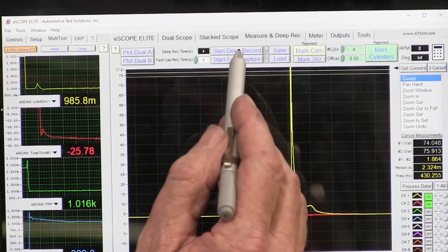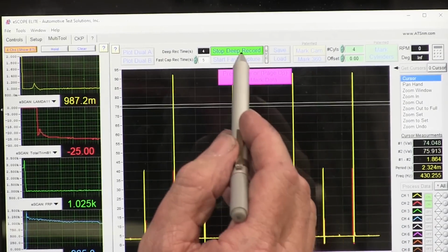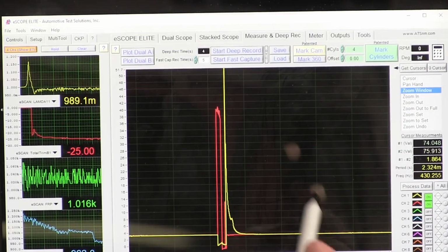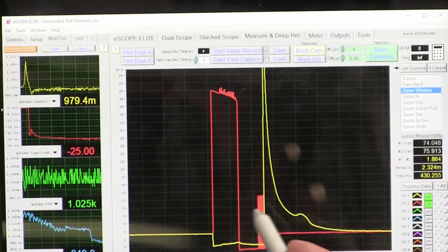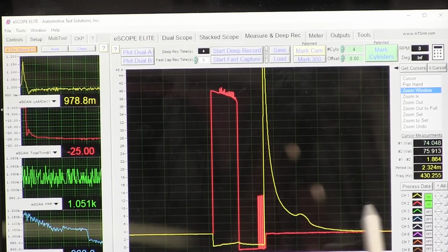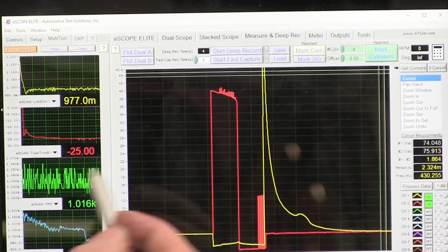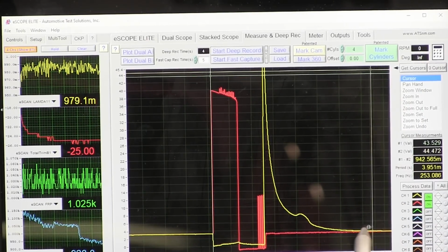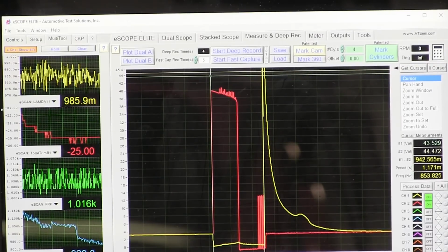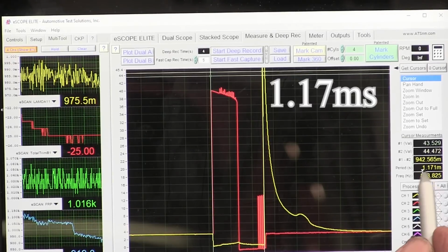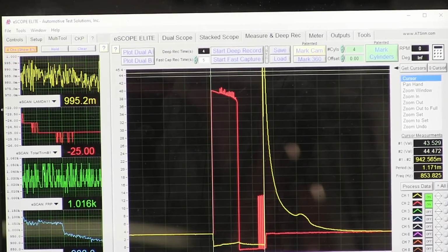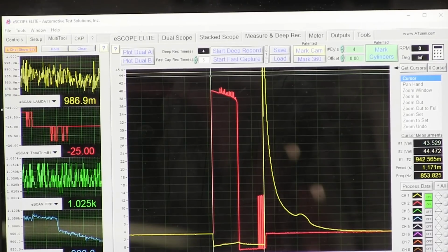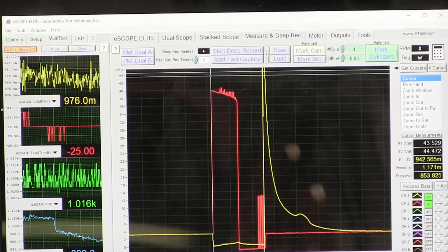Let's go ahead and get some more data. Now that it's run just a little bit, let's see what we get. And we can already see it's coming down. See how I have fewer, that I'm coming down because I'm taking away 25% trim already. 0.7 milliseconds on time now. But what's really interesting is this car came up with 2.5 milliseconds of on time to get it started.